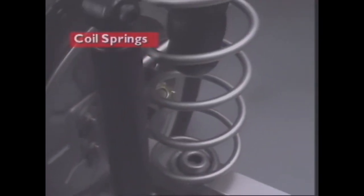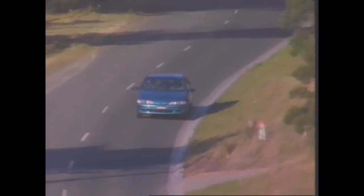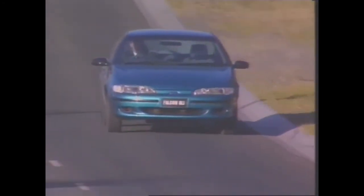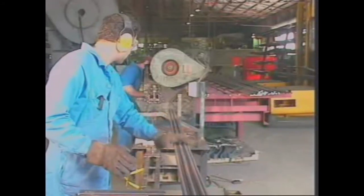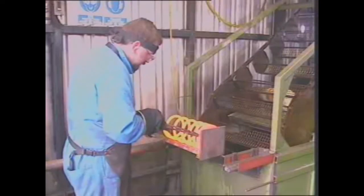This section examines coil springs. Coil springs are used on the front suspension of most modern light vehicles, and in many cases, they have replaced leaf springs in the rear suspension. A coil spring is made from a single length of special wire, which is heated and wound on a former to produce the required shape.